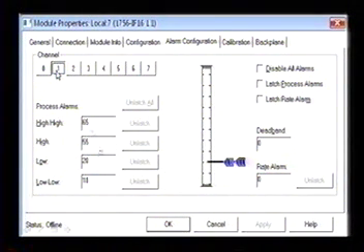Now this one's set up kind of goofy, it's not a 0 to 100% condition, but that's neither here nor there. This is a high value. It gives you a process alarm high. A high is 55, a low is 20, and a low low is 18. And if you click this, it'll disable those alarms. So you don't want to do that. You want to make sure that you are set up on your actual input card.